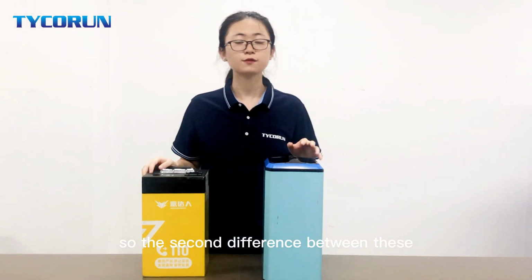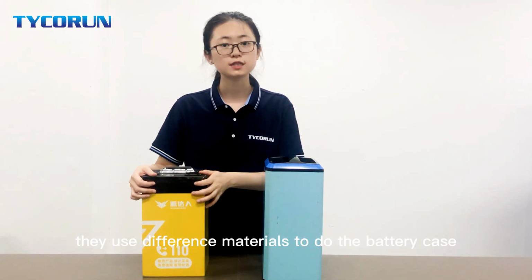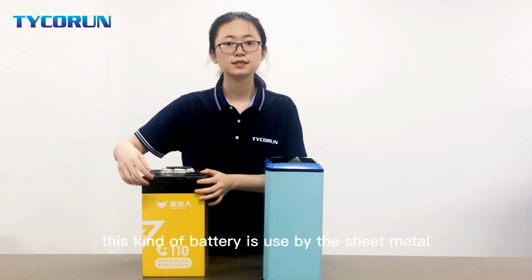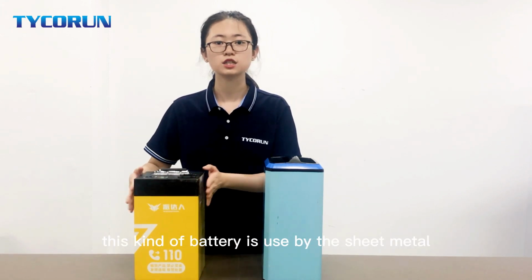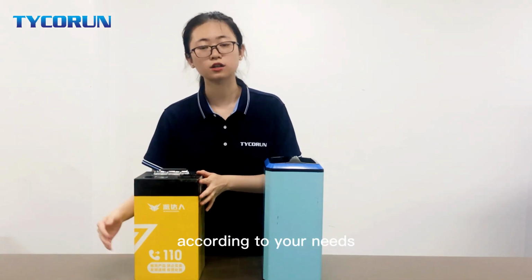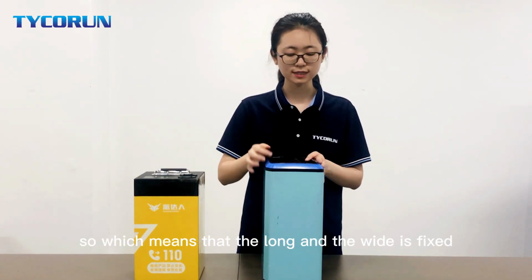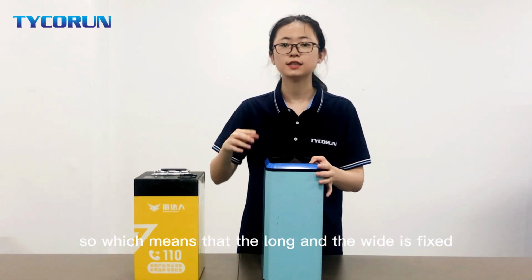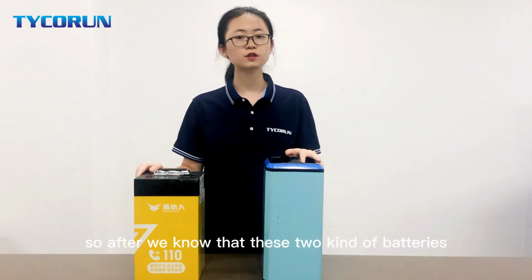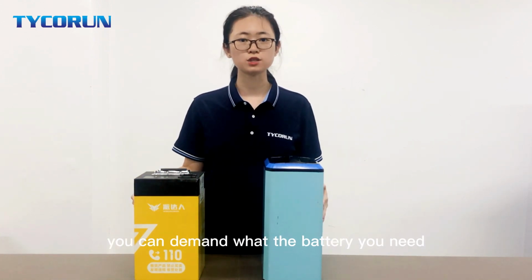So the second difference between these two kinds of battery is that they use different materials for the battery case. You can see that this kind of battery uses sheet metal, which means that you can design the length, the width, and the height according to your needs. And this kind uses plastic, which means that the length and the width are fixed, and you can only change the height. So after we know these two kinds of batteries, you can decide which battery you need.